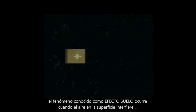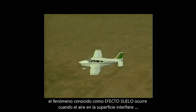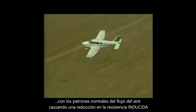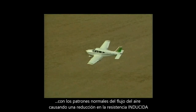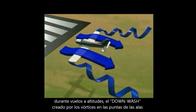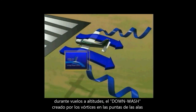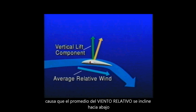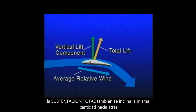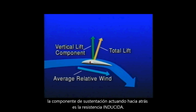The phenomenon known as ground effect occurs when the Earth's surface interferes with normal airflow patterns, thus causing a reduction in induced drag. During flight at altitude, the downwash created by wingtip vortices causes the average relative wind to be inclined downward. Because lift acts perpendicular to the average relative wind, total lift is inclined aft by the same amount. The component of lift acting in a rearward direction is induced drag.